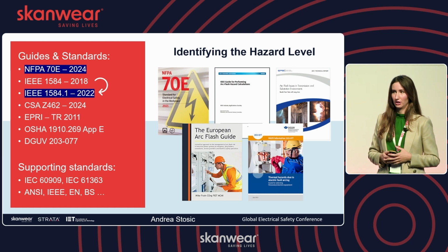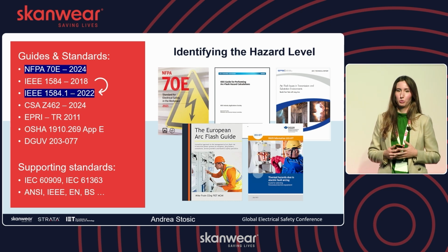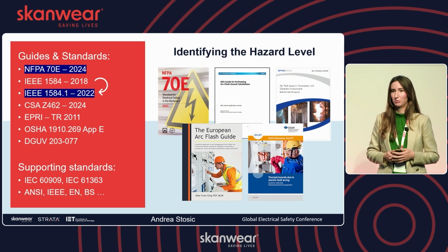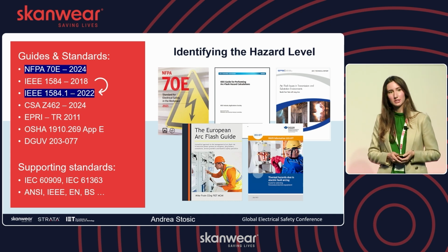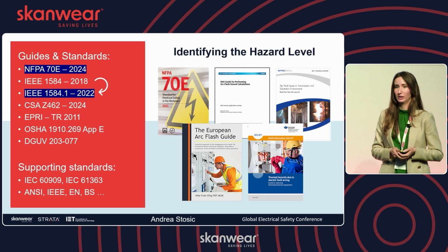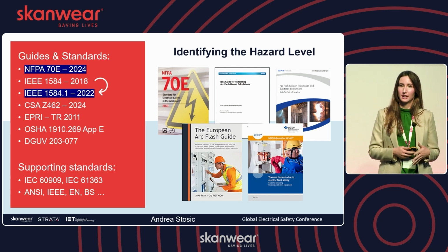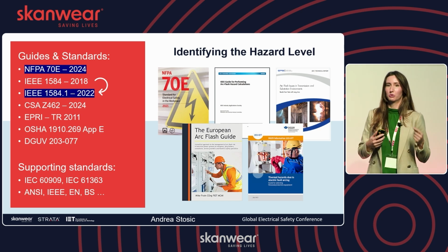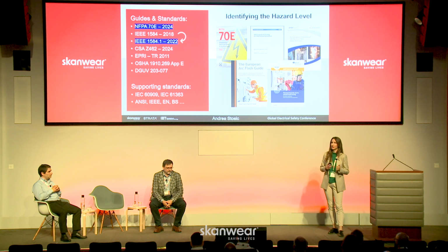It's a pretty good standard if you want to understand more about the PPE categories and about safety in electrical operations in general. A further important guide would be the IEEE 1584, which is a guide for performing arc flash studies. I would say it's equally important for consultants working on arc flash studies and calculations as it is for someone such as myself who works client side but guides the process, reviews the studies, and works with the consultants as well. You can also see on this slide an example of a Canadian standard, further to US standards, and a German guide for selecting PPE levels.